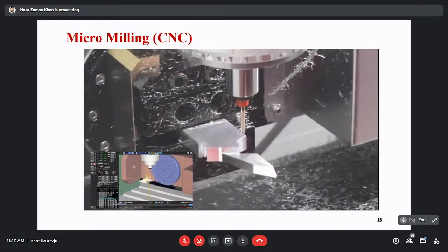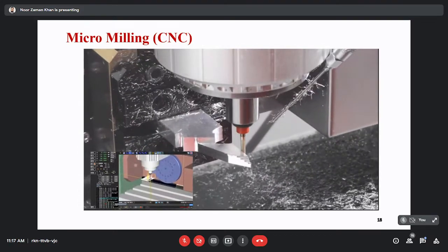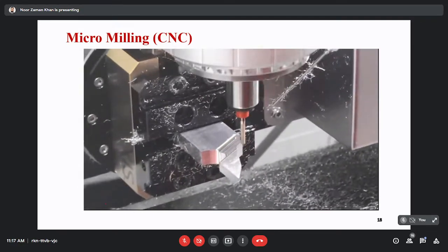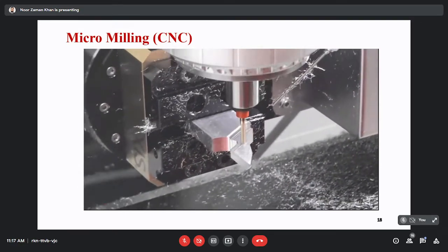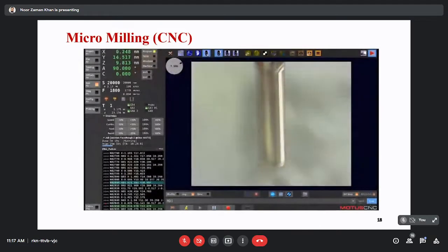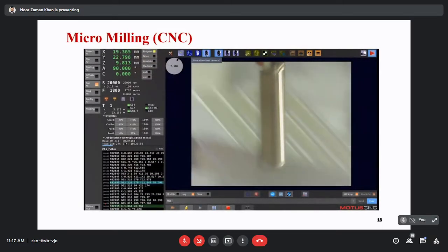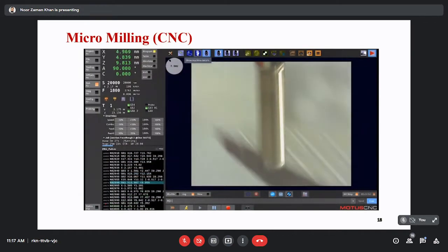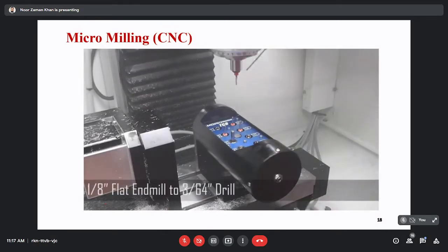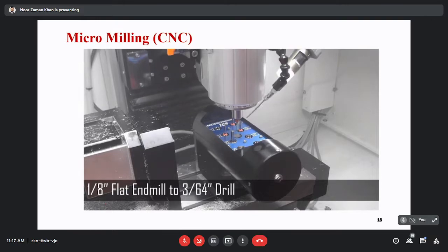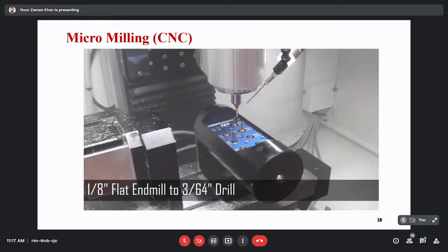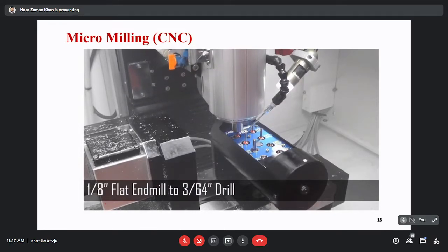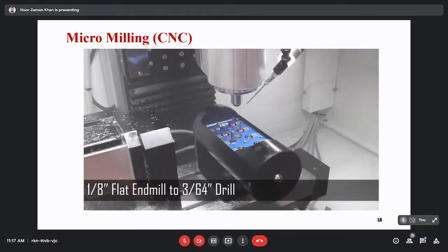If we use a very small end mill, cutting forces generally act while machining. So how to avoid tool breakage? I have performed a micro slotting operation with a 200 micrometer end mill, and we used around 3 to 4 end mills. To reduce tool breakage, you need to decrease the cutting depth and check the run out. If the tool breaks at the beginning of the machining, decrease the plunging feed rate, and use a coating to improve the tool life.